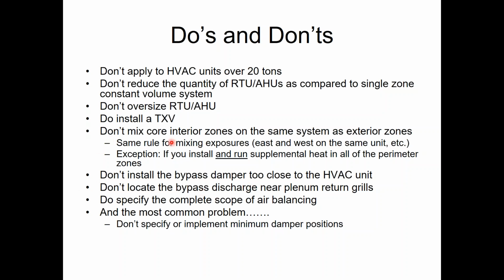Do not mix interior and perimeter. I think I've said it like 7 times. Do not mix interior and perimeter. Do not mix east with west. Avoid that when you can. If you're forced to do it for some reason, make sure all the perimeter zones have supplemental heat. If you're forced to do it and no one will pay for supplemental heat, do not do the job. Walk away. It'll be a nightmare, I promise you.